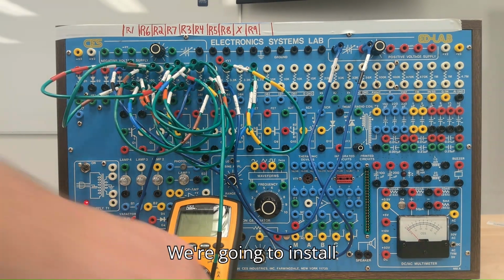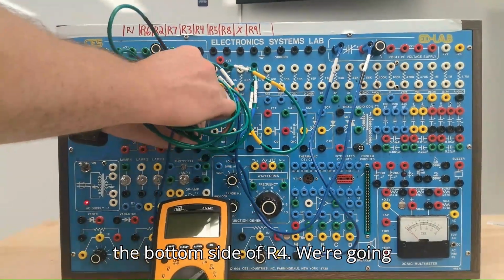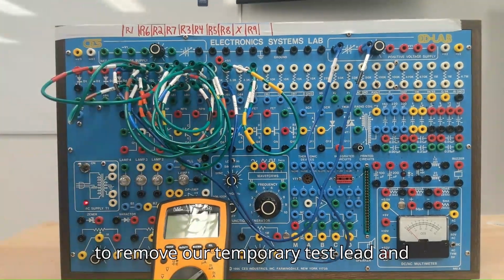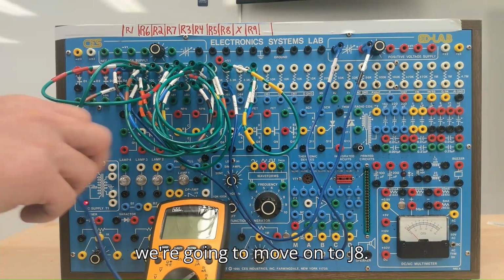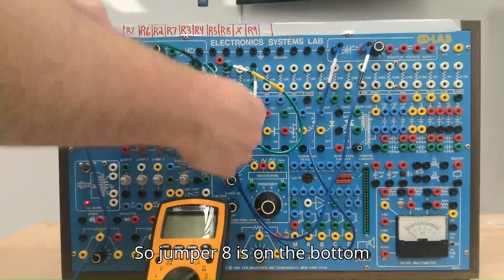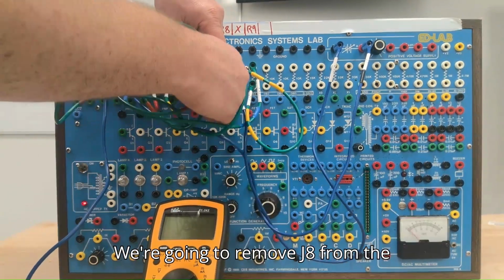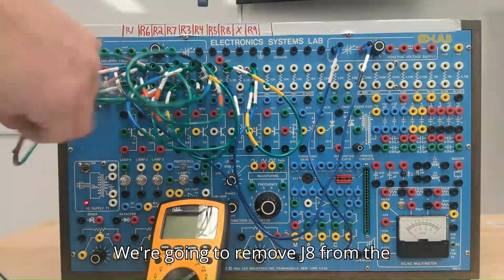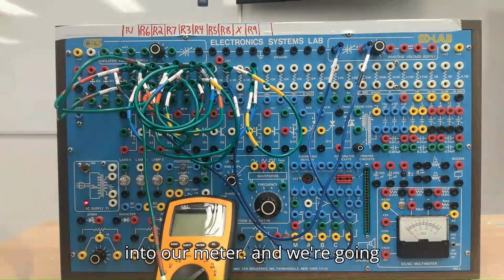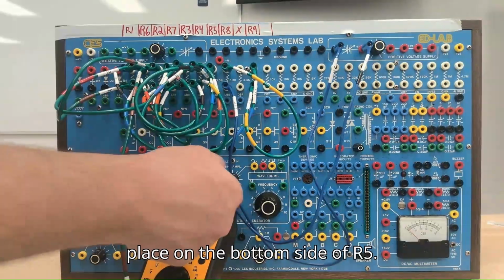We're going to install jumper 7 back into our circuit. Jumper 7 was on the bottom side of R4. We're going to remove our temporary test lead, and we're going to move on to J8. Jumper 8 is on the bottom side of resistor 5. We're going to remove J8 from the bottom side of resistor 5, install that into our meter, and install the temporary lead in its place on the bottom side of R5.